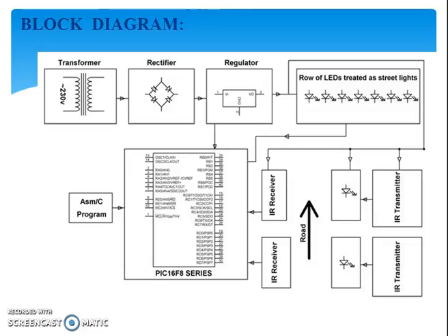The PIR sensor internally has an IR detector. Every object in the world radiates some IR rays. Those are invisible to the human eye, but electronic components can detect them. Different objects emit IR rays of different wavelengths. These rays are detected by the PIR sensor. The PIR output is initially high and is set to low automatically after some time. Whenever it detects the motion of any object, it becomes low.